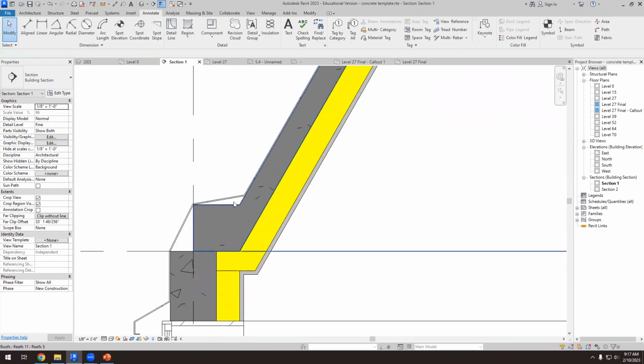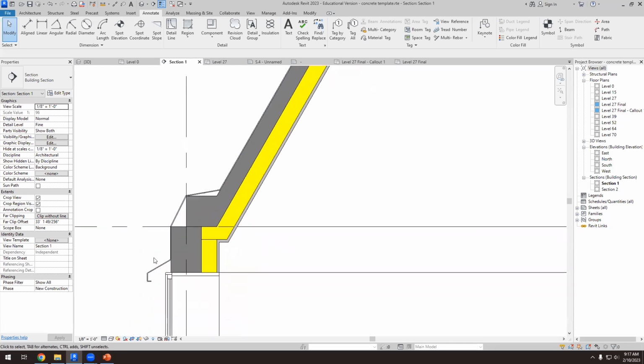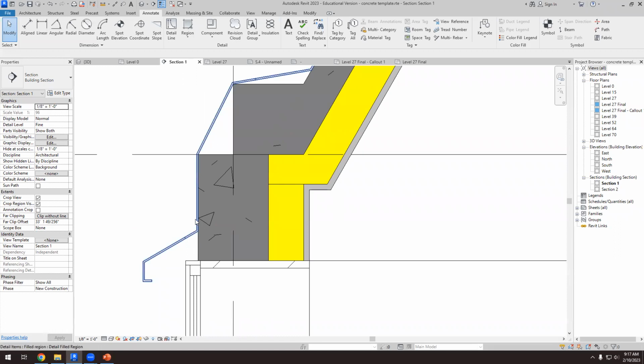That's even better, because if we have this horizontal, the water can stay here. If we have a slope, the water always goes down, and that's important. We can't let the water go vertically to the facade. We have to move it out, and we have to prevent the water from going back here. So we interrupt this here, and the water goes down again.